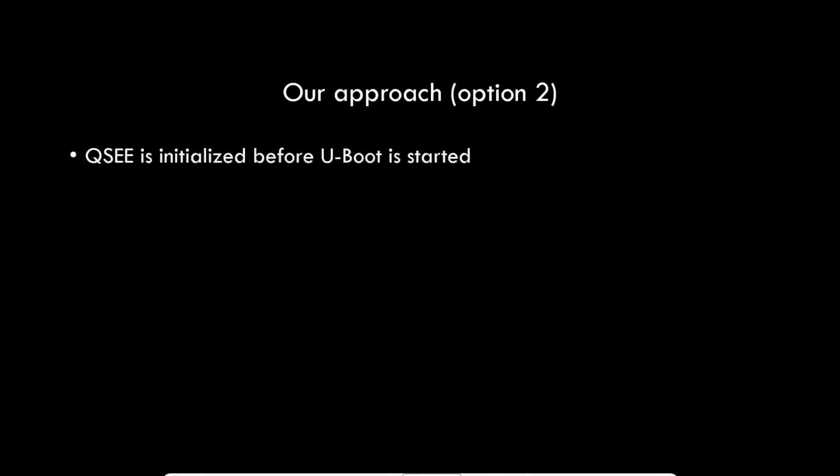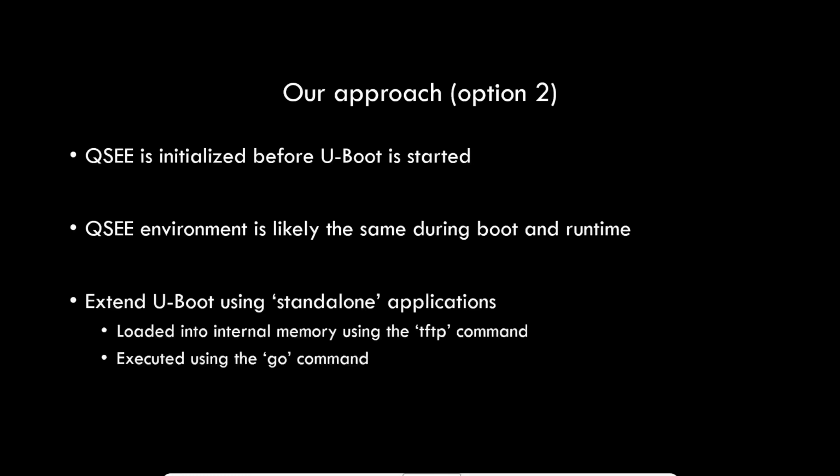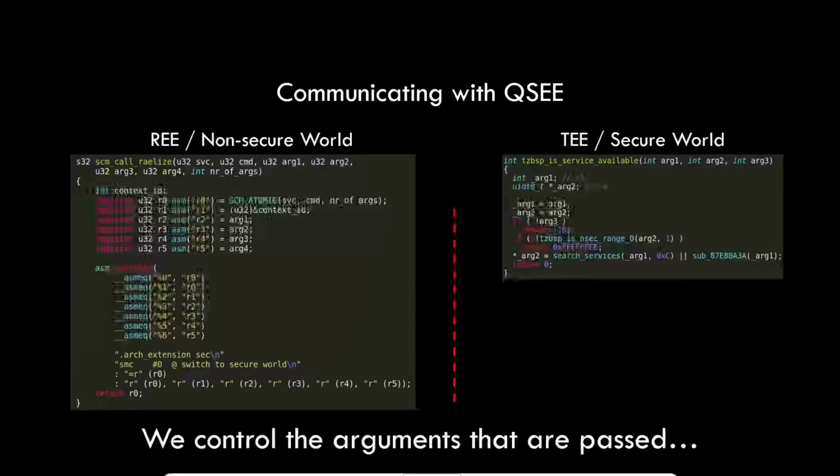Because QSEE is already fully initialized before U-boot is started, and we assume that the environment is pretty much the same. And this is usually, let's say, not a safe assumption, but a reasonable assumption. You should check that, of course. And U-boot provides some features where you can use a standalone application. So you can load your code into memory using the TFTP command, and you can just jump into it. So for us, it was quite easy to extend the running U-boot by having the ability to run our arbitrary code. Just compiled, loaded into memory, and using the go command in order to execute our own code.